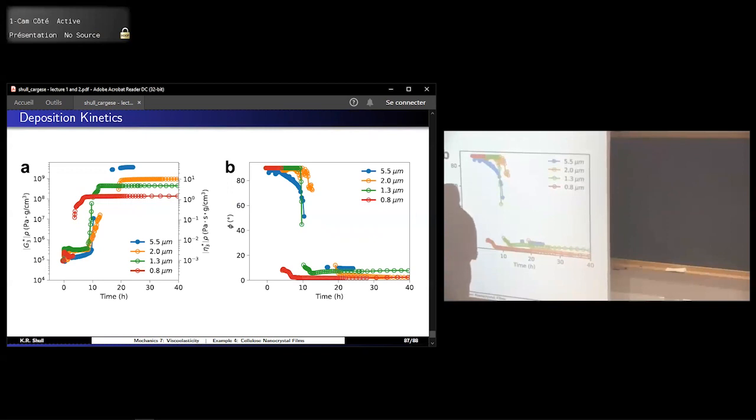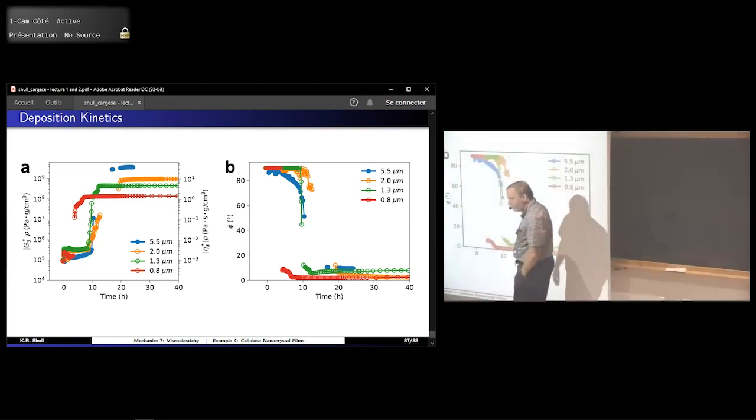You can use AFM indentation and measure the modulus on both sides. It doesn't quite work out that way, because as soon as you do the indentation, you're looking at the free surface again. So there's no way to really get at the properties of a confined surface in contact with our substrate. But I think the sensible explanation here is that there is a layer at the top, which is just softer.